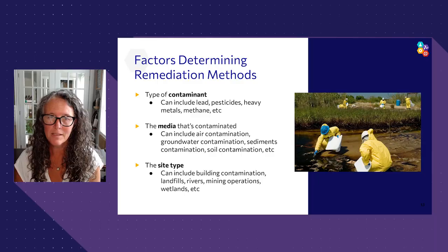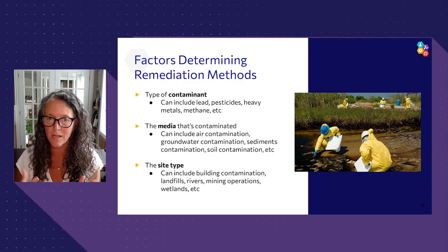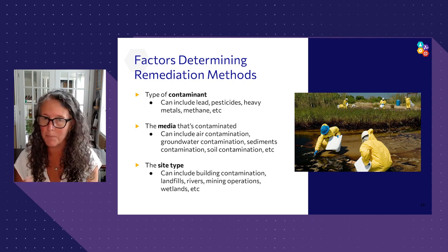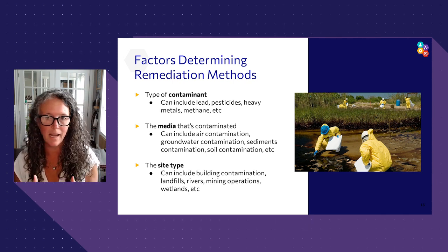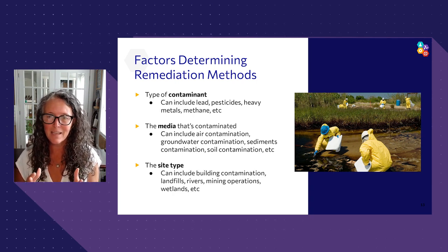So when you're determining which remediation methods you're going to use, you really have to understand the type of contaminant. You can't apply the same technique to any contaminant because they don't all behave the same way. That's where the engineers and scientists have to really work together to understand the behavior of the contaminant, and also the media that you're trying to clean up. Is it water? Is it soil? Is it air? Or is it a combination of all these things? And then lastly, the site.